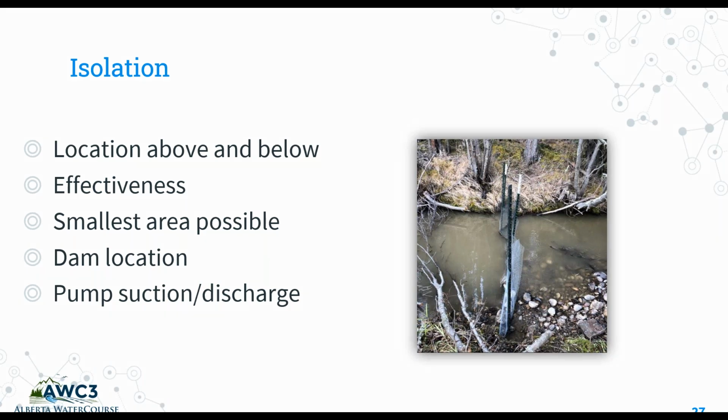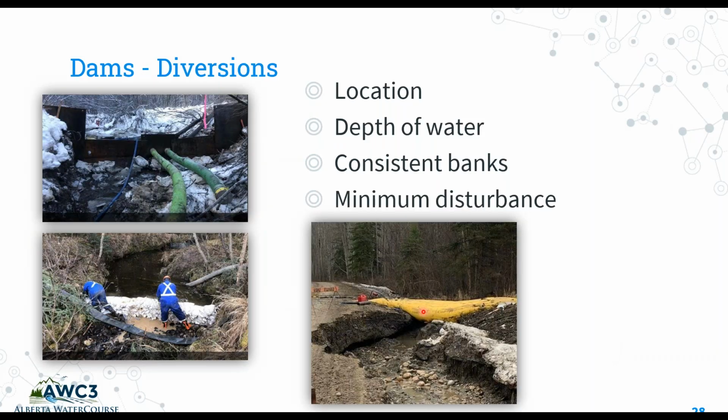Dams and diversions, again, location, where are you placing your dam? How deep is the water? How deep do you need the water to be? Your dam can be installed to make the water deep enough for your suctions on your pumps. Are you putting it in a place where the banks are consistent? Are we minimizing disturbance when we are installing our dams?